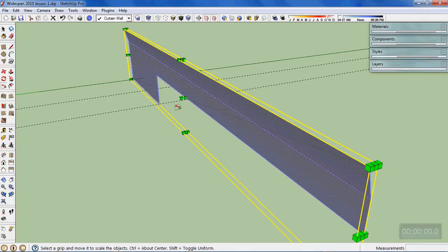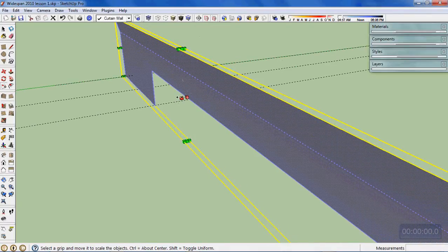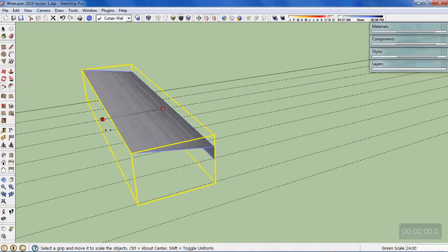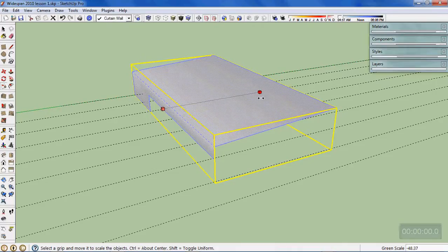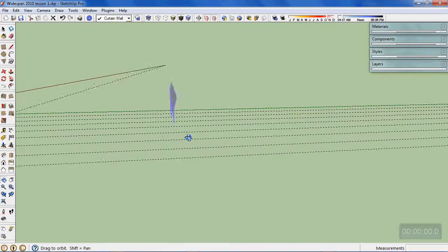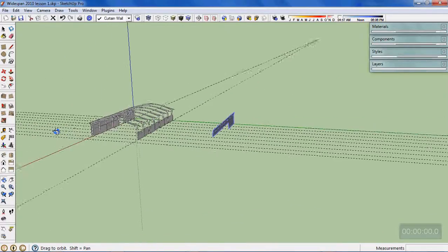What we want to do is we actually want to pick up this one on this face. So if we very carefully pick up this one on this face, that'll actually only scale in that direction. So if I click on one of those, you can zoom out, you can see what you were doing there. Now what I want to do is I actually want to scale back in the other direction, and the amount that I want to scale it by, so as I'm stretching it out in the other direction, if I just type -1 and press enter, I've now just mirror imaged that around by flipping it back 1 in the other direction, negative. Yeah, so I've basically just mirrored it around.